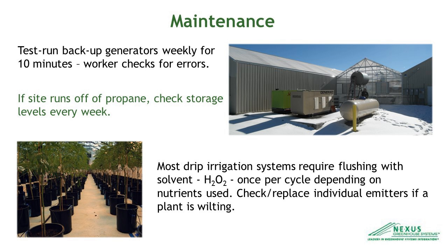Most folks will have 2 drip emitters per pot, and so if an emitter should get clogged up, the plant's not starving for water for a few days, and you need to see the signs of that plant wilting, check that emitter and replace it if it is.